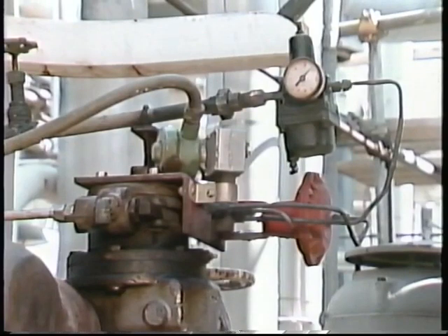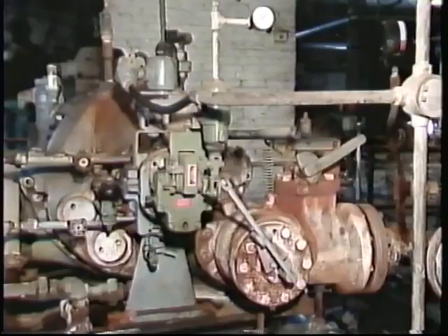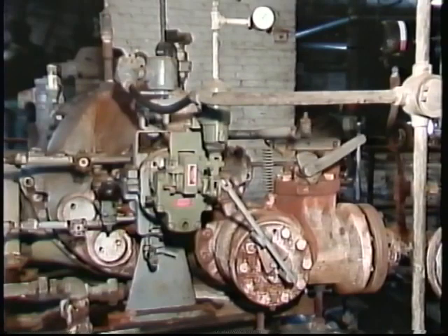Some turbines have additional protective devices that will automatically shut the turbine down if an unsafe operating condition develops. These protective devices are commonly triggered by conditions like low lube oil pressure, high bearing temperatures, or some other abnormal condition associated with operation of the turbine, the equipment driven by the turbine, or the system in which the turbine is used. Typically, such devices involve a solenoid trip that is operated by electrical inputs from the system that has developed the abnormal condition. In this example, a turbine drives a pump.